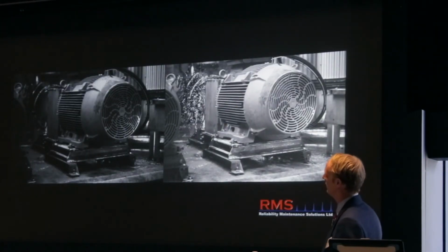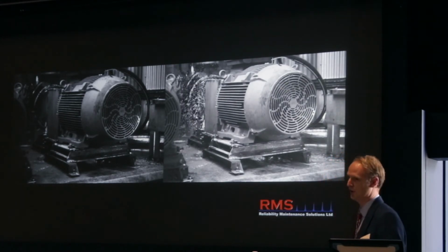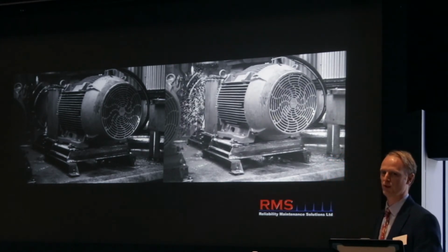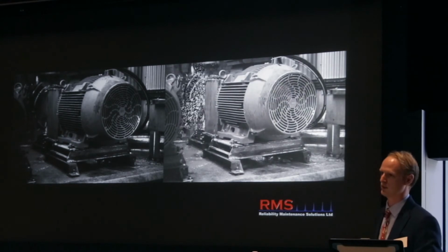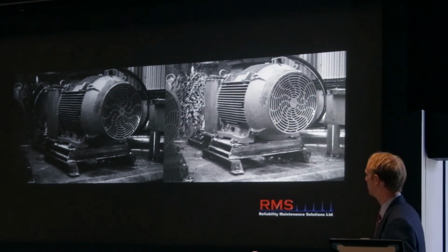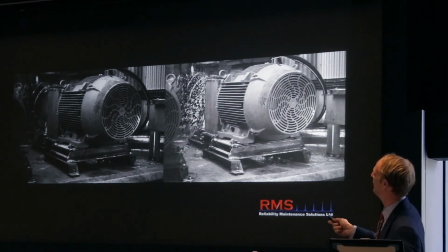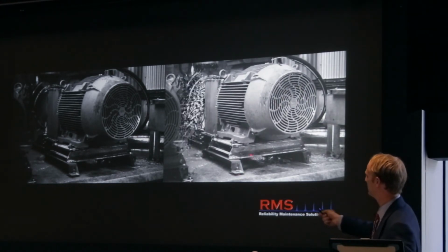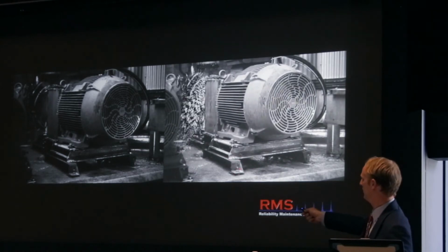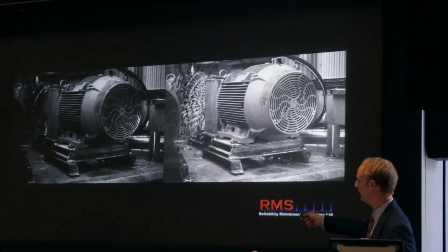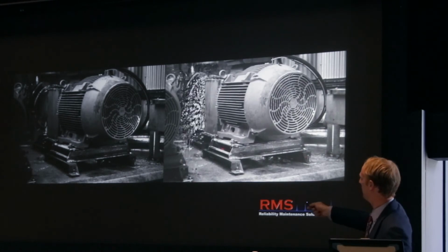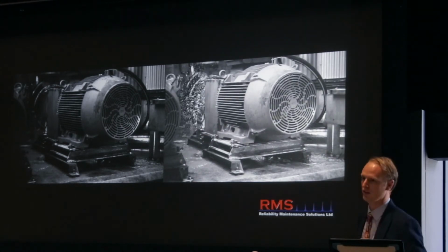We can go to a brand new machine that's just been installed and identify an issue before it's commissioned and allowed to be handed over to maintenance. On the left-hand side is the video, it's playing, but on the right-hand side, the dramatic things you can see, instantly your eyes are drawn to where the base is really poor quality, it's weak anyway, and it's got these looseness parts on it, and also there's a seal failure straight away.